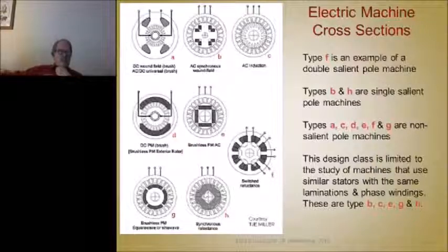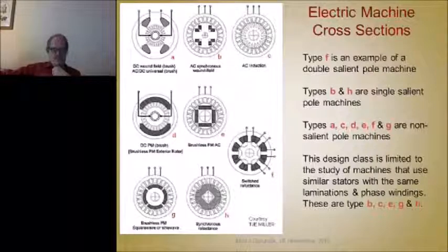So in reluctance machines, the torque and performance you get is based upon how well you can create this saliency, or how big of a difference you can design into the geometry such that one inductance is a lot higher than the other one. So the inductance ratio is equivalent to the saliency ratio in these kind of machines. So that's what I wanted to point out.